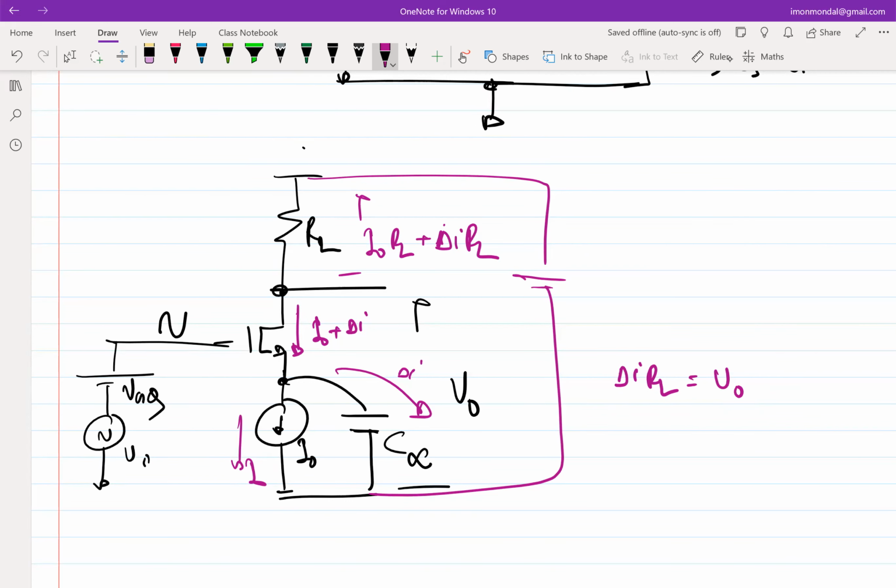But since this is an AC, a sinusoidal current, it's not getting enough time to ramp up or ramp down before the next cycle starts. Hence, C infinity acts like a short circuit. You can say that Vs is not able to keep up with the gate voltage change within that limited amount of time.